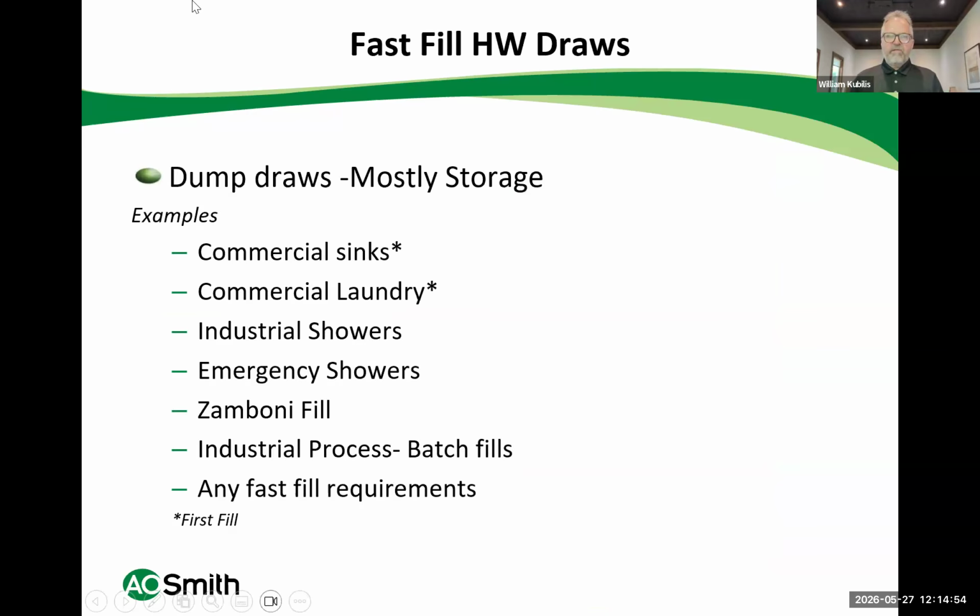Good examples of when you need storage is what we call dump draws. Commercial sinks. If I'm filling a commercial sink, they want to fill it fast, and having the water in storage for that is important. Commercial laundry. They want to fill a laundry machine quickly. They don't want to wait for one tankless water heater to spend 20 minutes to fill. They want to fill it quickly.